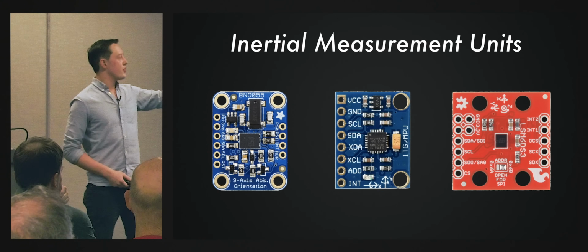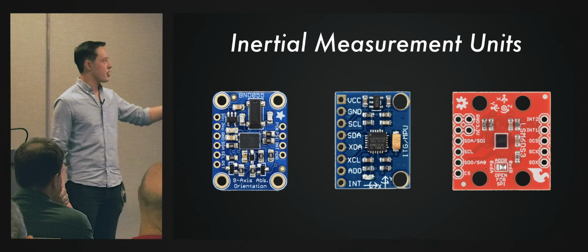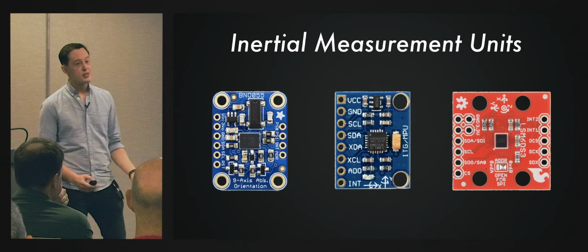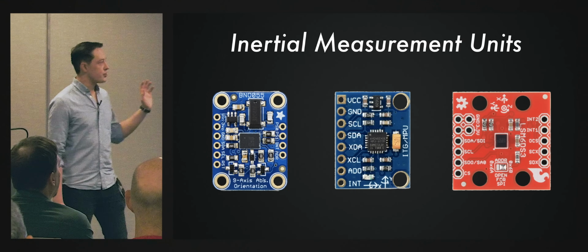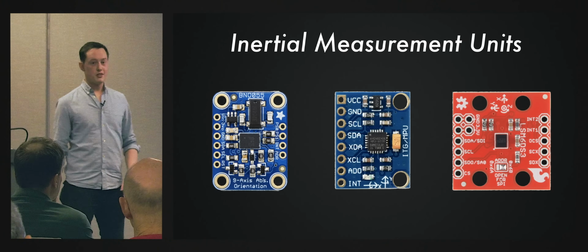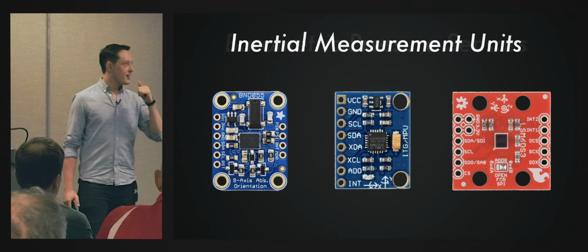The BNO055 is a little bit more expensive because it includes a lot of microcode, or micro software, on board that helps you get the orientation of your vehicle, and the gyros and accelerometers are slightly higher quality. You do get what you pay for. But they're all roughly the same quality speaking. And they will all totally work for thrust vector controlled model rockets, at least at low power. Don't fly these on an M motor.